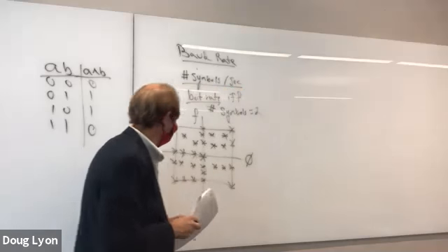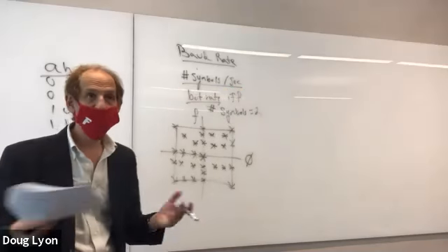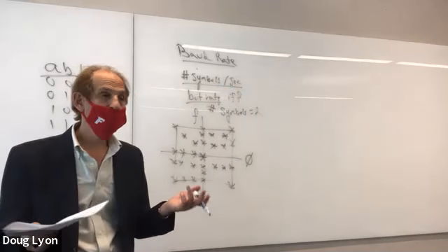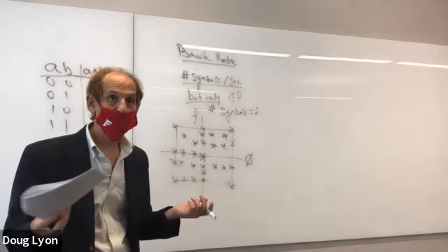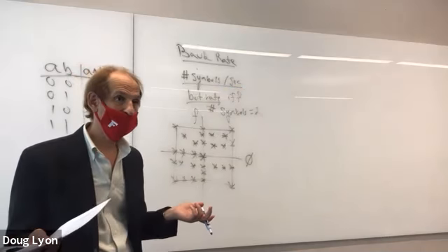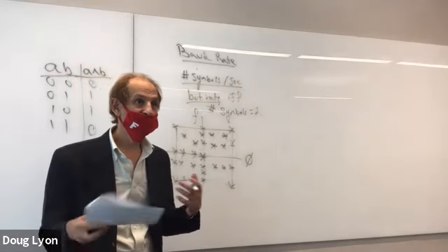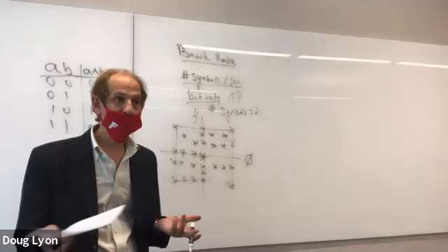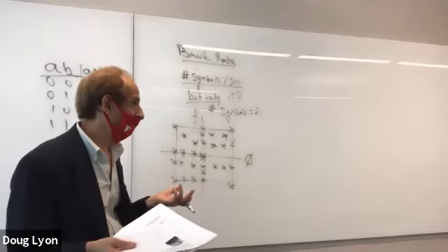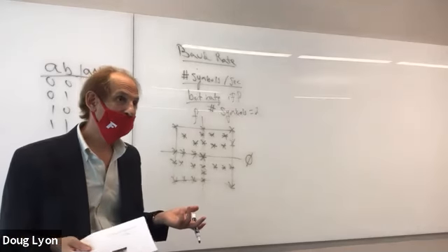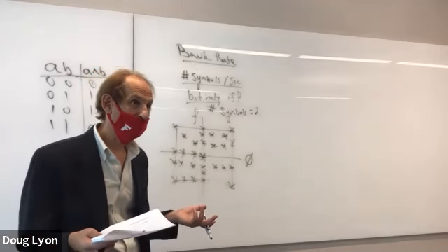Maybe there's more. So if I have 16 symbols, then each symbol, if they're all equally probable, is worth log to the base 2 of 16, which is equal to 4 bits, because 2 to the 4 is equal to 16. So you're getting 4 bits per symbol. So if I send you 10 symbols per second, your equivalent bit rate is actually 4 times that, or 40 bits per second.